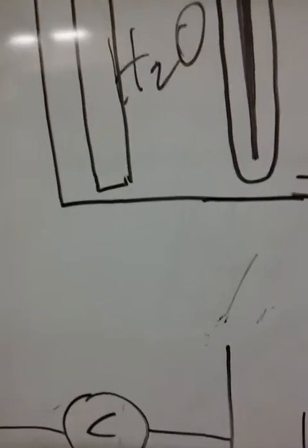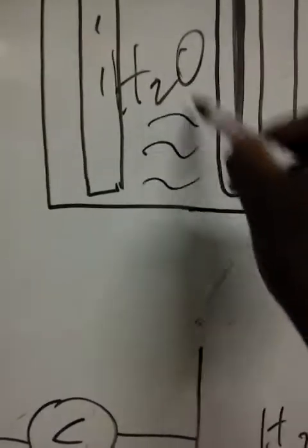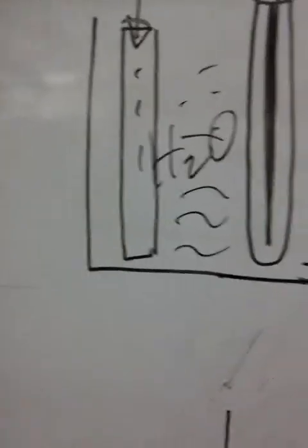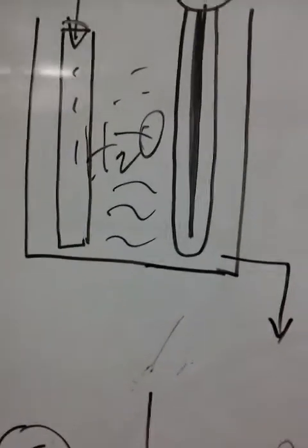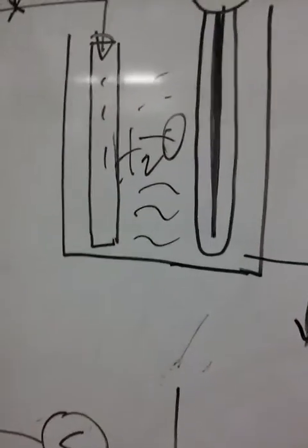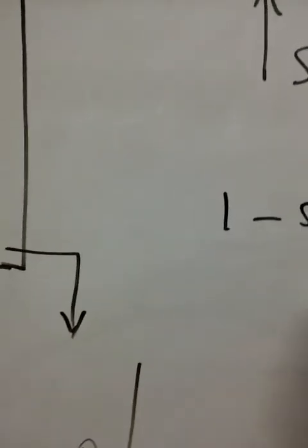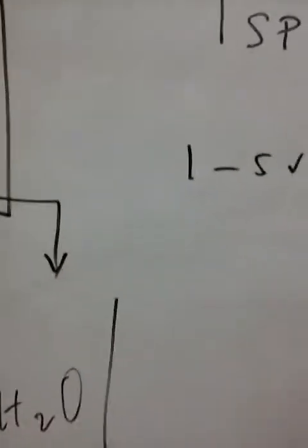Then I'll answer question 3, where we need to understand the principle of operation, how this works. By adding a second probe, we're creating a capacitance in between the probes. Now, with the increase of process, which is water, of liquid in this tank, there is a change of capacitance. This change of capacitance normally induces a signal output from the sensor, which is 1 to 5 volts. And this signal is proportional to the level in the tank.